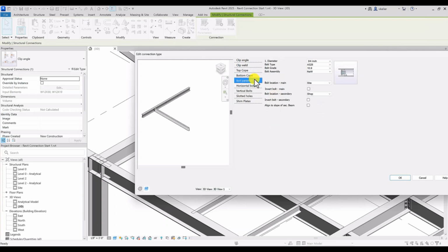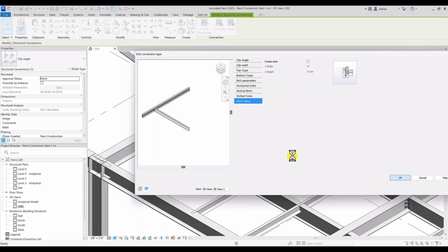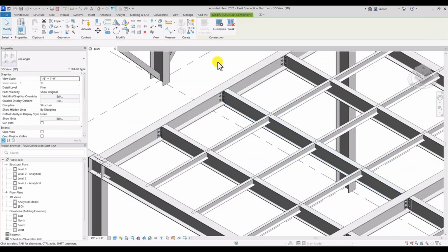And sometimes you got to be careful of this. So say I want all the back marks to be 2 inches instead of 1 3/4 on either side. I can zoom into that little previewer, which is kind of nice too. And the only way I can see it in the model is click OK, get out of it, and see the change. Through here, we do at least have a little preview window to give me an idea of what I'm doing. Okay, and they all have changed together.